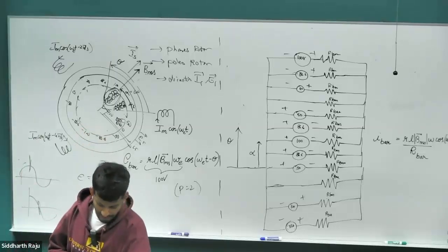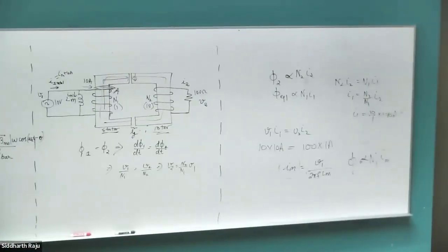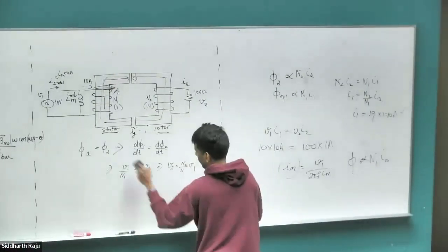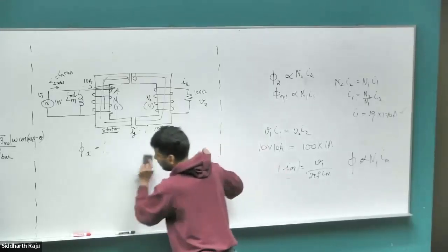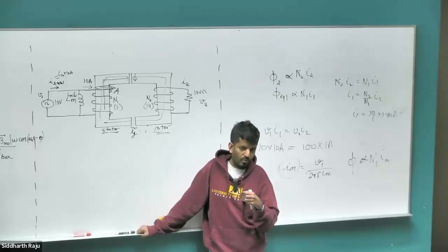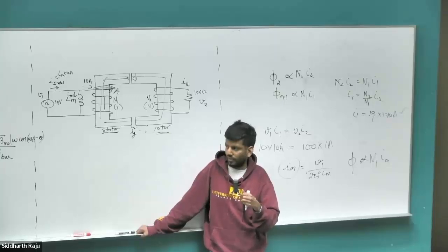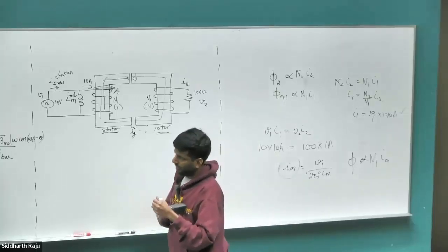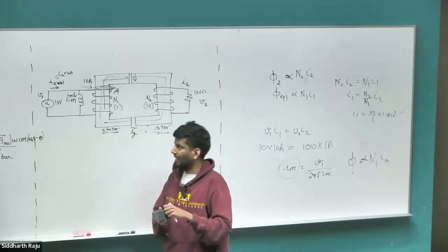So the only flux in the air gap for an induction motor will just be the stator current induced flux alone, with no contribution coming from the rotor currents. Do we have any questions? A very critical point, because in a permanent magnet synchronous motor it differs quite a bit, because there are two distinct B fields which are independent and which operate simultaneously. In this case, there is just one set of B field that's going to be in the air gap for this ideal case.